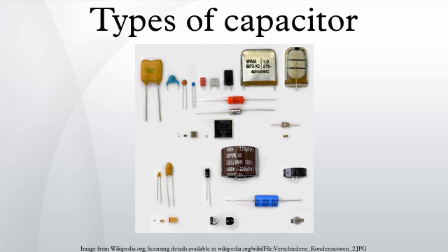For metallized film capacitors, so-called pulse tests simulate the pulse load that might occur during an application, according to a standard specification. IEC 60384 Part 1 specifies that the test circuit is charged and discharged intermittently. The test voltage corresponds to the rated DC voltage and the test comprises 10,000 pulses with a repetition frequency of 1 Hz. The pulse stress capacity is the pulse rise time. The rated pulse rise time is specified as 1/10 of the test pulse rise time.